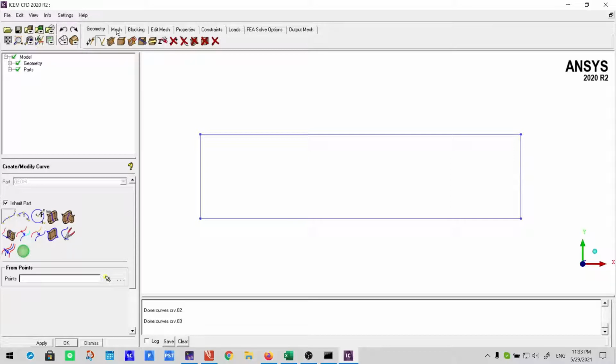You can see here it is a mesh tab. Let's see global mesh, surface mesh, and other meshing options are there, that compute mesh and all. But I generally don't like this because this produces unstructured mesh and consumes a lot of RAM. This is an automated meshing, and I won't suggest it. It's good meshing, but not really required for the structural meshes.